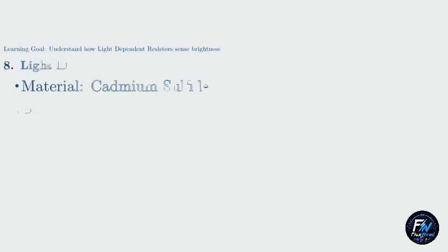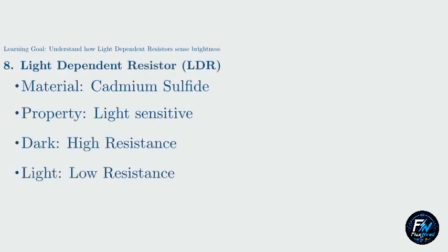Imagine a streetlight that turns on automatically at dusk. This is often made possible by the light-dependent resistor, or LDR. The LDR, also known as a photoresistor, is made of a light-sensitive semiconductor material like cadmium sulfide. When light photons hit the wavy track on the surface, they knock electrons loose, making it easier for electricity to flow. In total darkness, an LDR might have a resistance of several million ohms, but under bright sunlight, that resistance can drop to just a few hundred ohms.